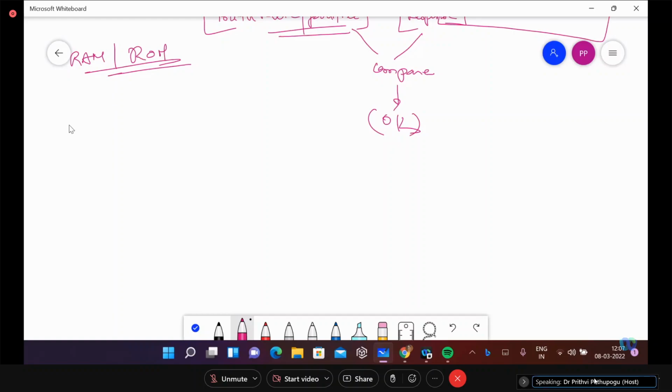Like this built-in self-test, why we go for the BIST setup is that the more the number of transistors or components that are getting integrated, the more the complexity of the designs. And the more the complexity of the design, the denser will be the circuit board components. The denser the circuit board components, the more minute the paths for testing, and using literal probes to tap the data becomes very difficult or impossible at every segment on the board.